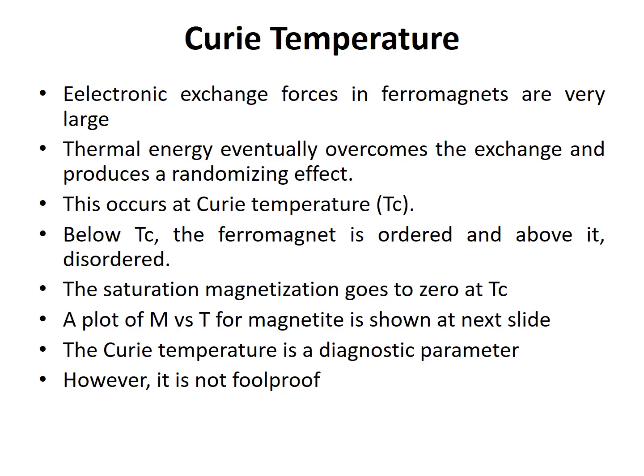Curie temperature is particular for different materials, as I told about the Curie temperature of three materials, iron, cobalt, and nickel, in my last lecture, I think. Iron has a Curie temperature of about 770, cobalt has 1100 and something, and the third material, nickel, has a Curie temperature of about 358, something like that. You can get the data from the previous lecture.